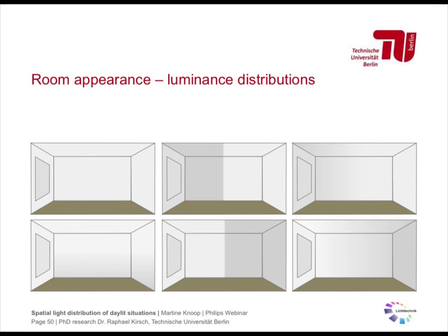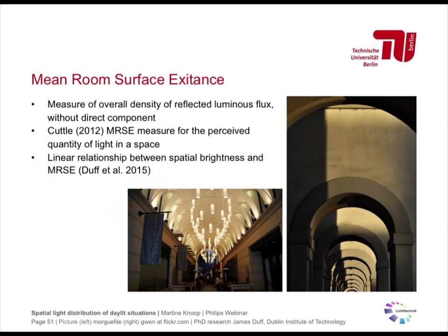At the moment, the intermediate conclusion is that visual lightness is highest when we have a uniform light distribution, but if we have a specific pattern or non-uniform distribution, the visual appraisal is higher. So non-uniform distributions are more interesting, but the room might be perceived as less bright. Of course, there are other people looking into the topic of room appearance and luminance of the wall.